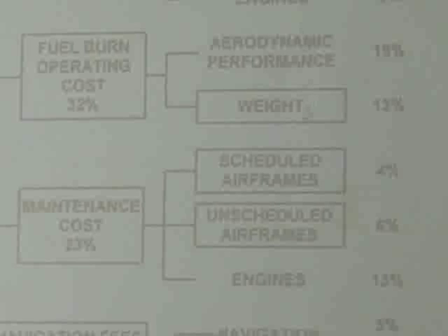Weight here essentially is the performance based on weight. So it costs as much fuel to run the aircraft as the whole manufacturing of it. And then it costs about 4 times more fuel than the material cost. So it just gives you some idea that you can be willing to put a little bit extra money in manufacturing if you can reduce your weight.